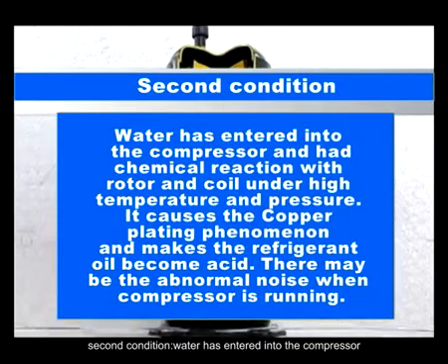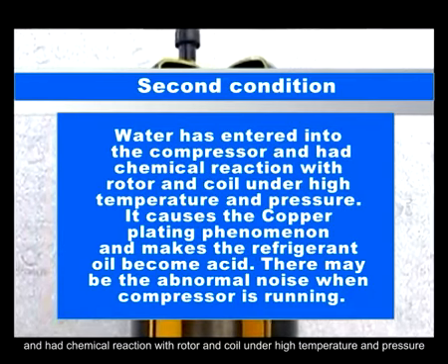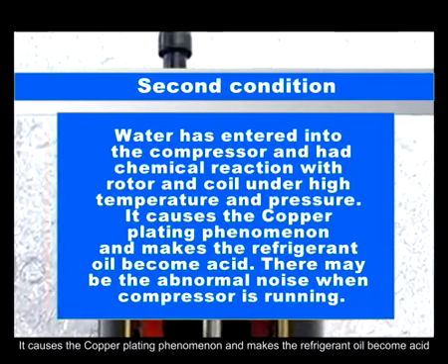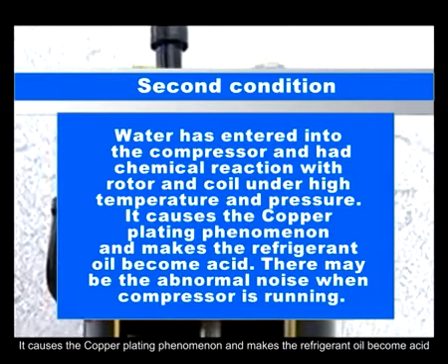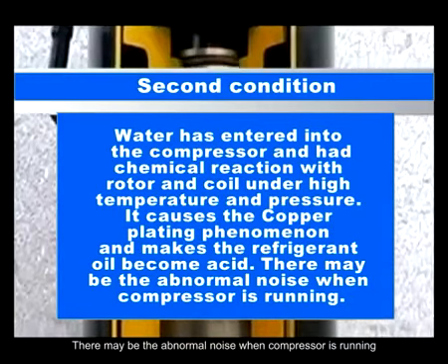Second condition. Water has entered into the compressor and had chemical reaction with rotor and coil under high temperature and pressure. It causes the copper plating phenomenon and makes the refrigerant oil become acid. There may be abnormal noise when compressor is running.